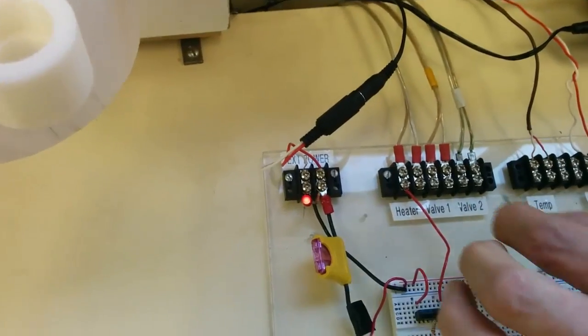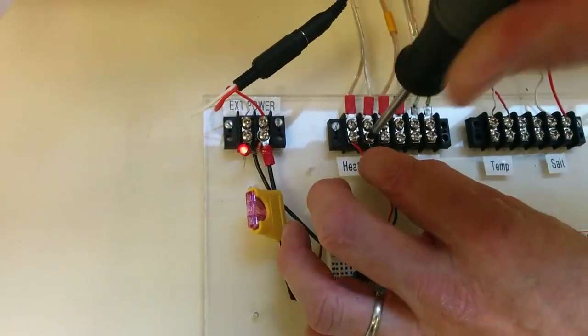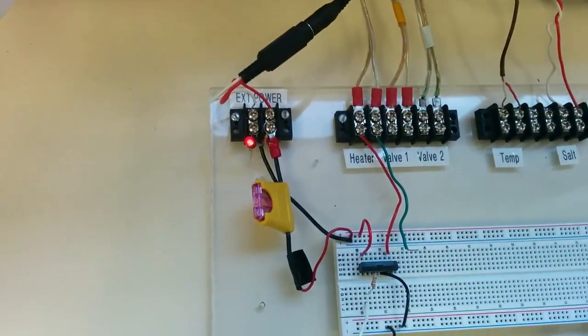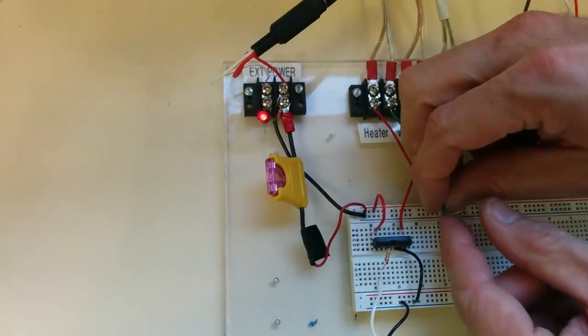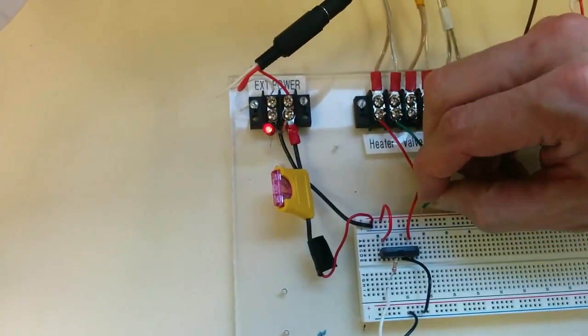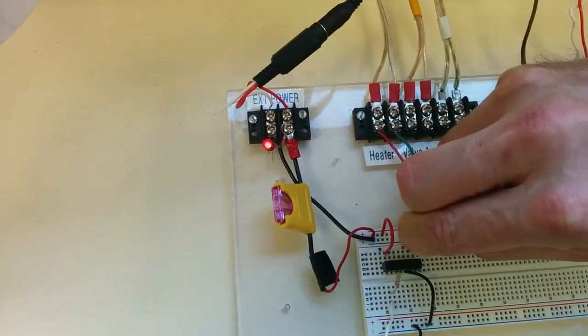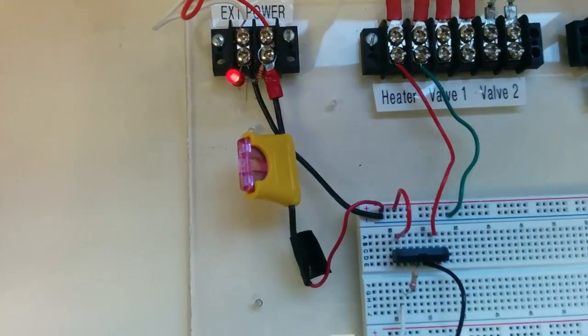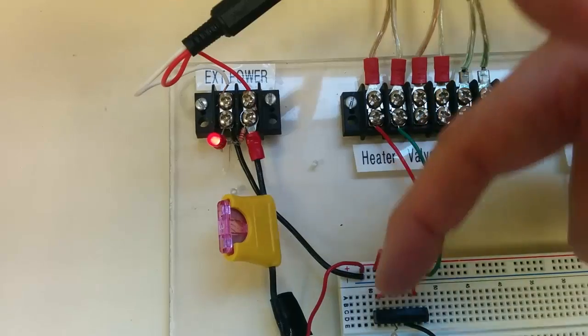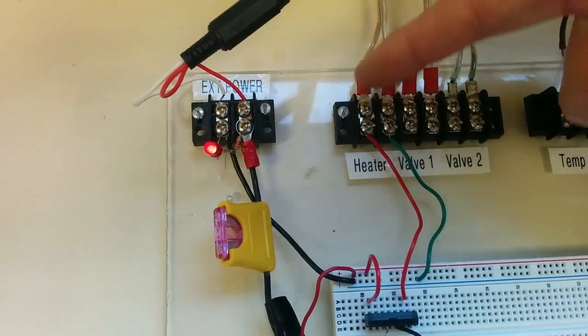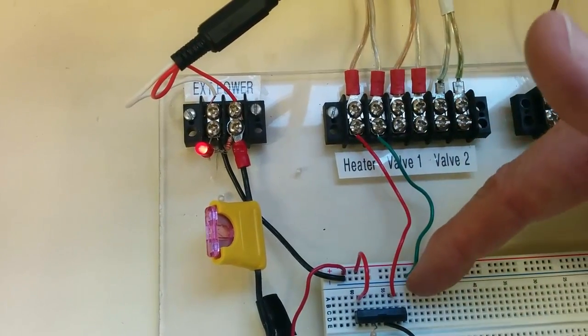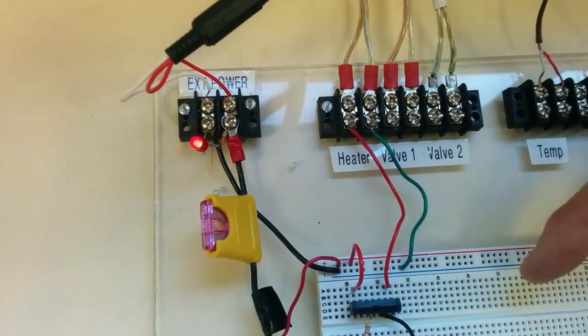So since this is the 12 volt power supply, we're going to use a slightly different color for ground. We're going to use the green just to keep things consistent, green for the secondary power ground and black for the primary, and we have to come right back to the ground. So again, we came out of the power supply through the switch, out through the load and back to ground. So that closes our secondary circuit.